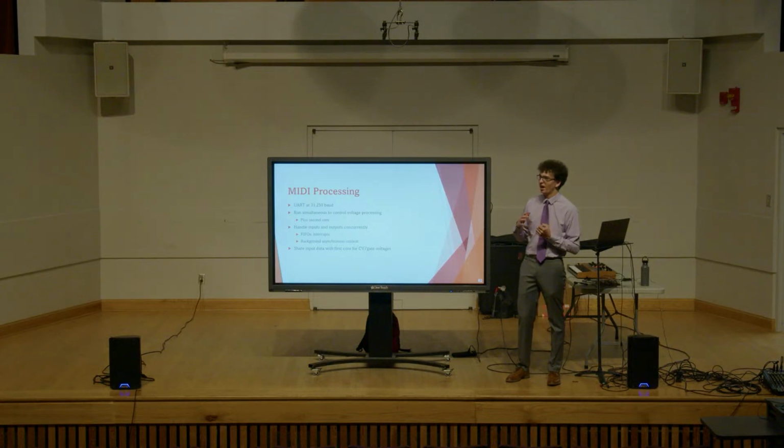And so, likewise to wanting to run the control voltages and the MIDI at the same time, I'd also like to run MIDI in and out at the same time. But if I'm running MIDI on one processor, that becomes a little bit harder. So what I also decided to do was implement interrupts on the MIDI input, which tell me if the input buffer on the Pico has a byte of data to read. That interrupt tells me, okay, there's an available byte of data. I program that interrupt to take that data, put it in a queue, and then return right to where the program was before it did that.